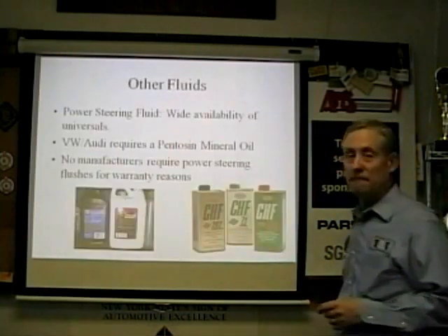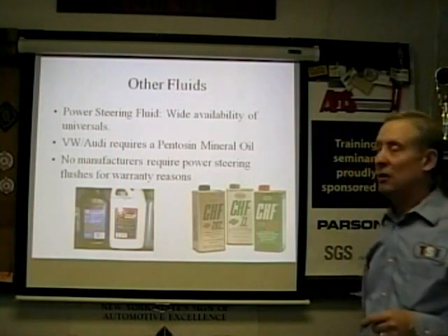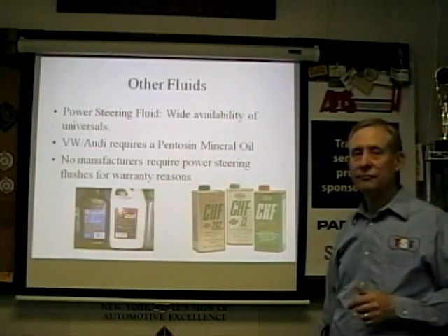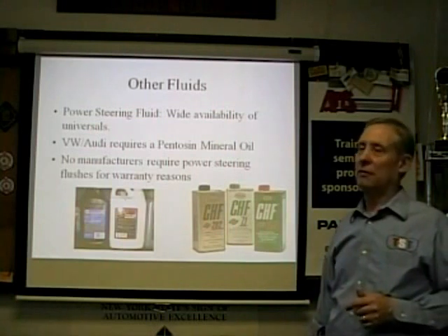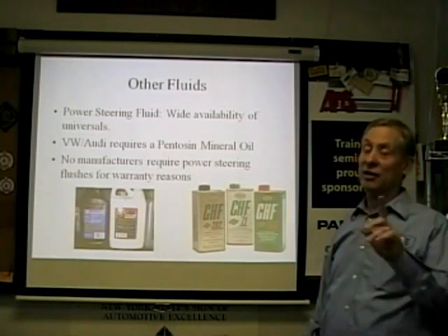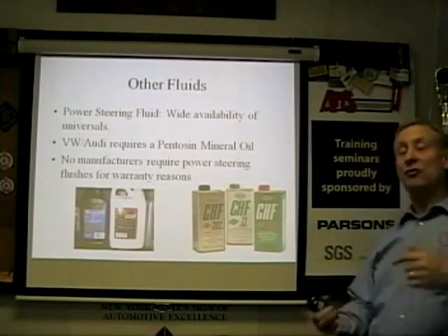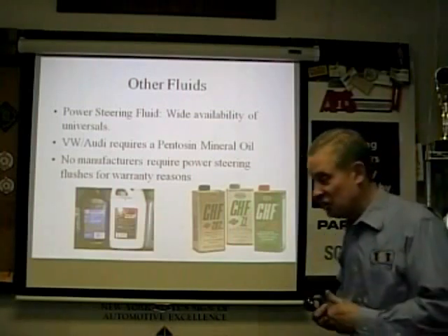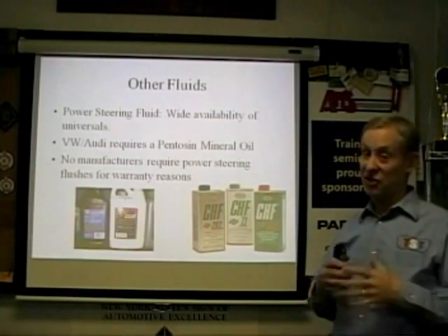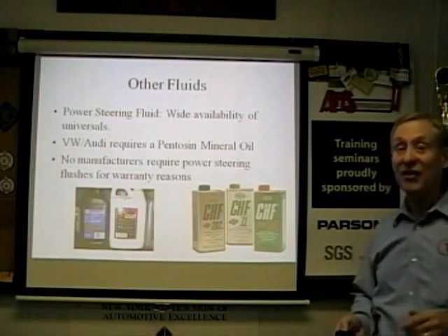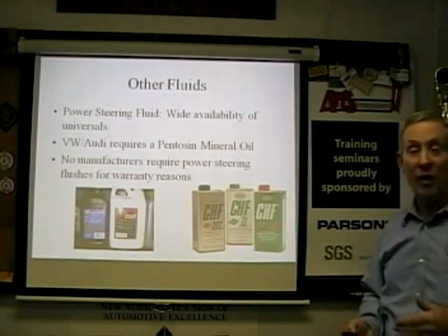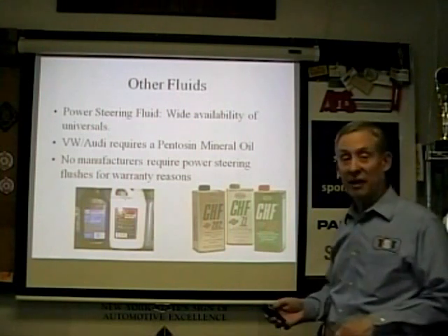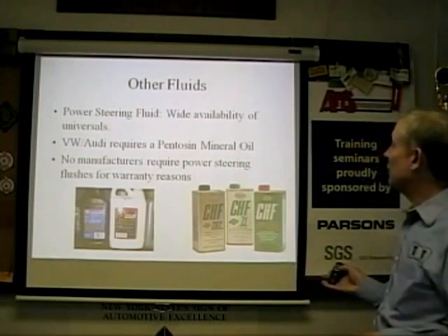And I guess we should also say you have to make sure you get all of the water or flush out of the coolant system to get a good fill. Actually, Jerry brings up a good point. If you're using a chemical flush, you got to make sure that stuff is gone. Can't leave any of that. Waste the water. Use the water. Get rid of it. Flush it out. Make sure it's all clean.